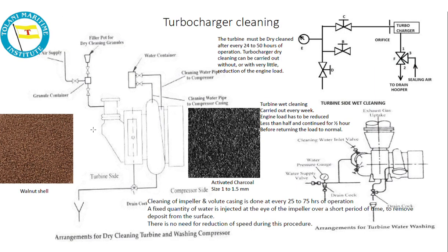Okay, now we go to turbocharger cleaning. Why we are doing this cleaning altogether: see, this is activated charcoal and this is walnut shell. This you must have often seen, and there is water washing as well. We have wet cleaning and we have dry cleaning.